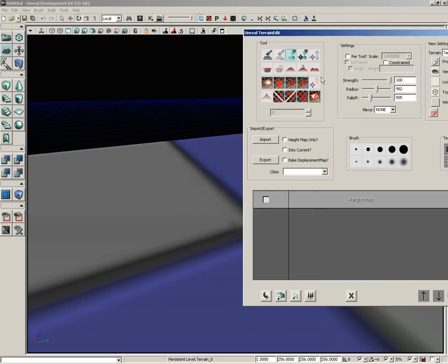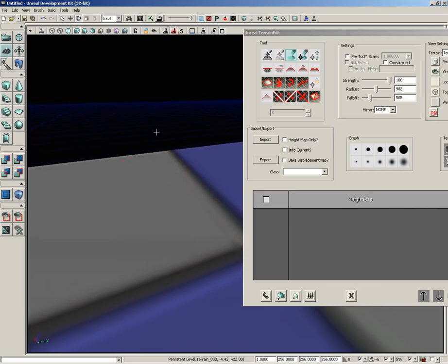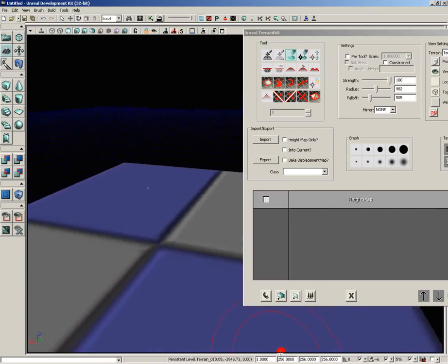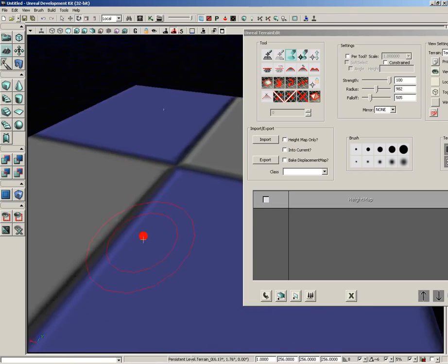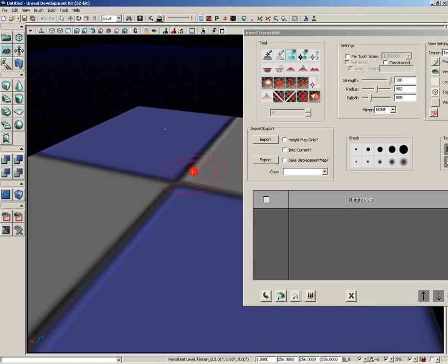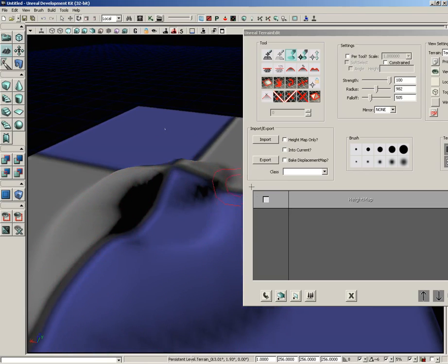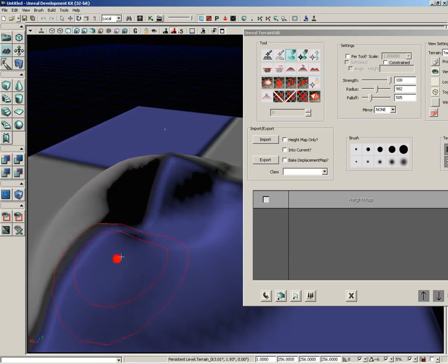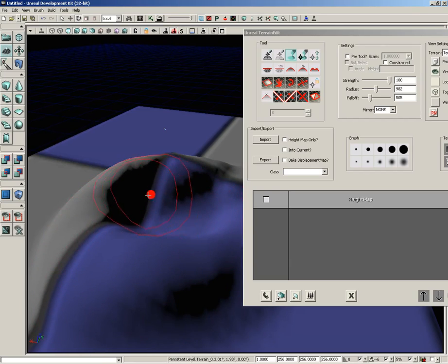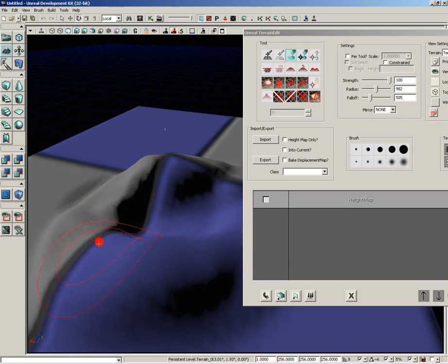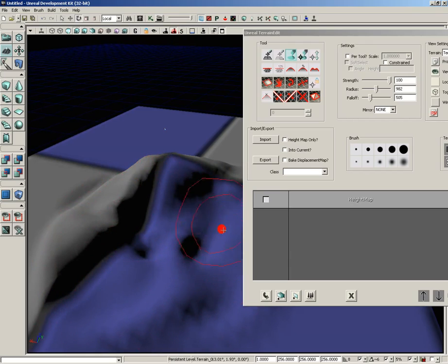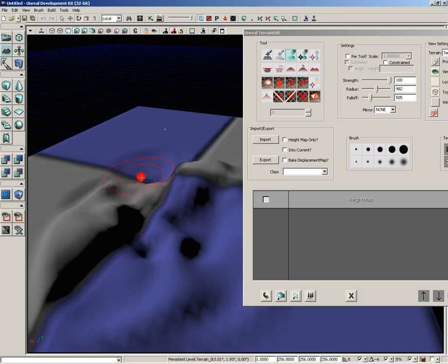As soon as we do that, if we mouse over the terrain, you'll notice we get this circular shape, and this is actually our brush. So I'm going to move the camera up into the air and pull back. Now, if I hold down the control key and drag across the surface, check it out. I can create a raised area. If, while holding control, I drag with the right mouse button instead of left, I can push back down. So already we've got a free-form surface that we can start to sculpt.